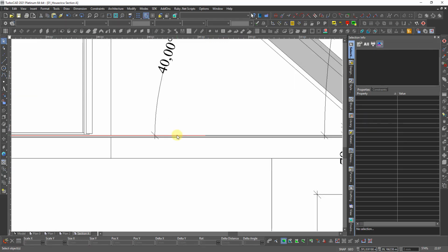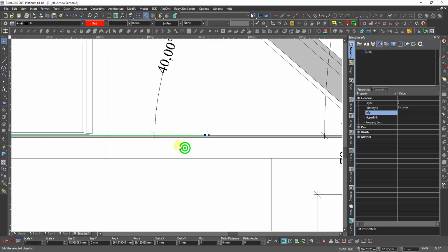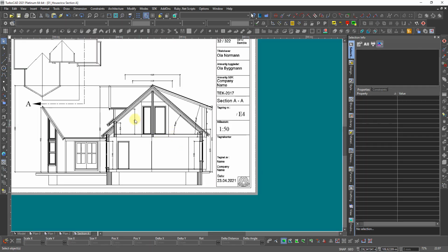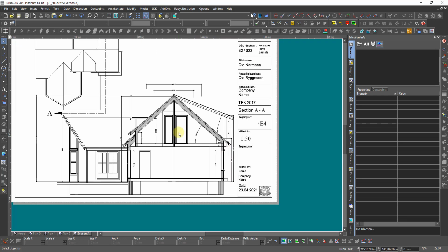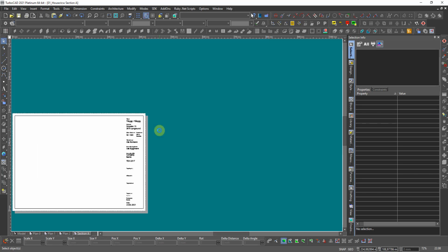The red line down here I also don't want to see. Turn connection, delete. So now they know I calculate for 1.9 meter, and there is this. And if I take 600 millimeter more out here, I have this. 600 on each side. That's how we calculate the area, and they should know when we give the area for the second story how many square meters is the real user area that they calculate. Then we have done it, and I think I'm finished with this.